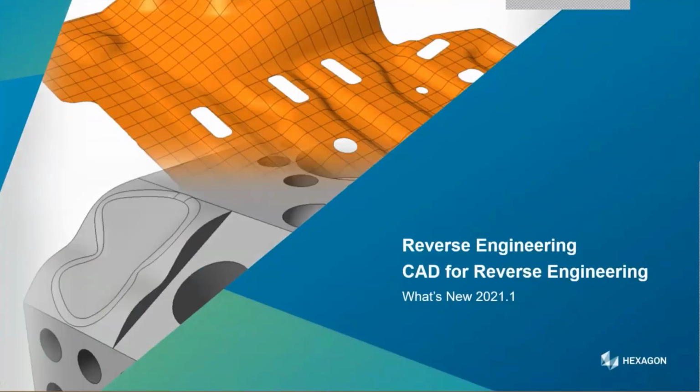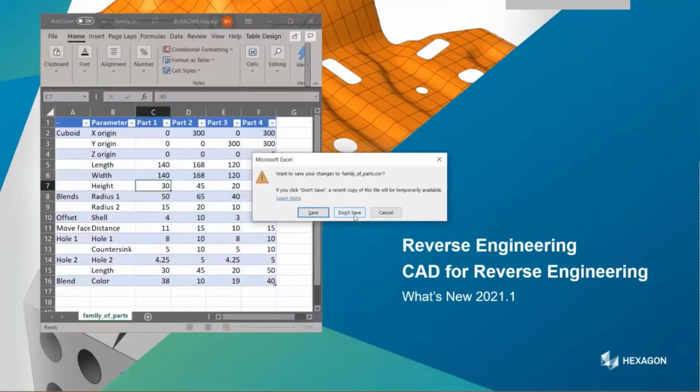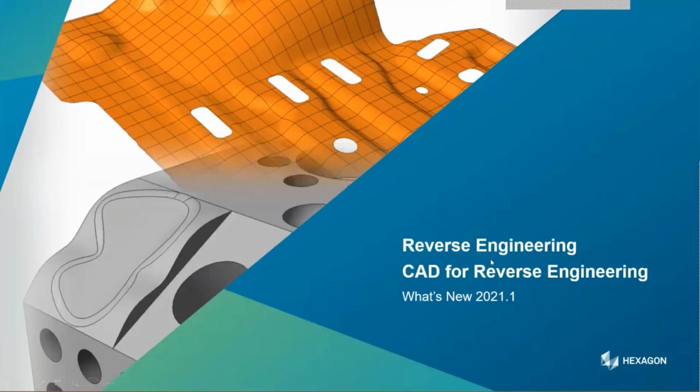So we had a question on one of those demos, so I'll just answer it now as we go, actually. It's easier while it's fresh in my mind. It would be nice if there was a hint for why the command cannot be applied. So often when we have operation not possible shown, it's a parasolid error, and the error message doesn't actually make any sense anyway. So operation not possible is often the best thing we can actually show. It doesn't always say why in the parasolid feedback. So we have investigated that before.